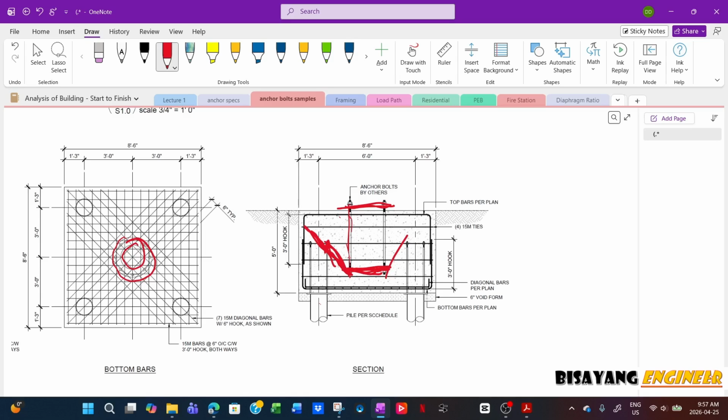usually, for a small pile cap, this is a Nelson stud shear connector. But for this one, this is 8 foot 6 wide by 5 foot deep. So I use a 3D rod here so I can have a longer length, because I think Nelson studs are only limited up to 12-inch length, if I remember correctly.